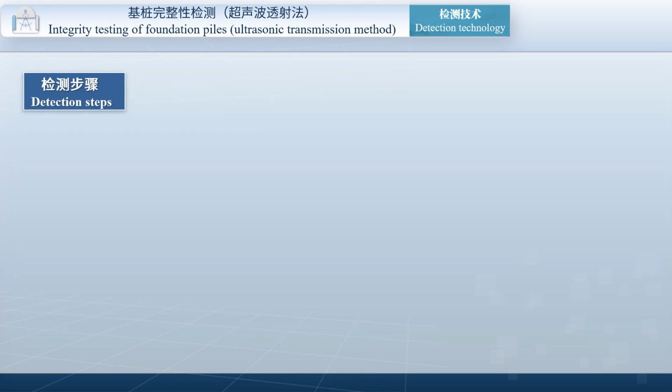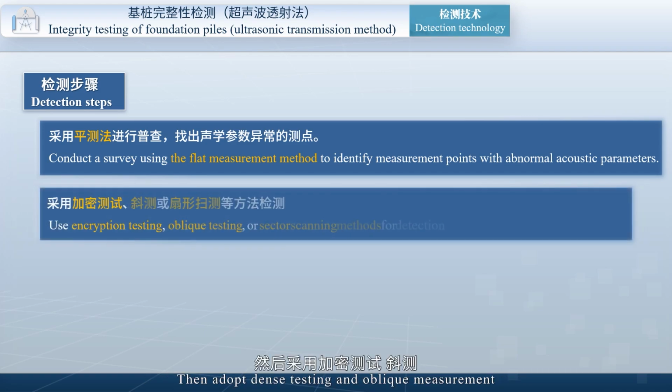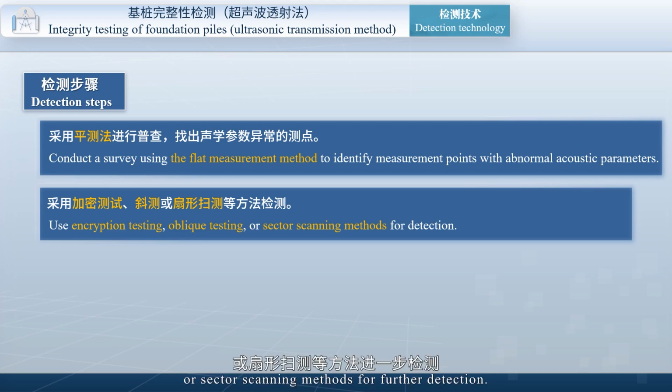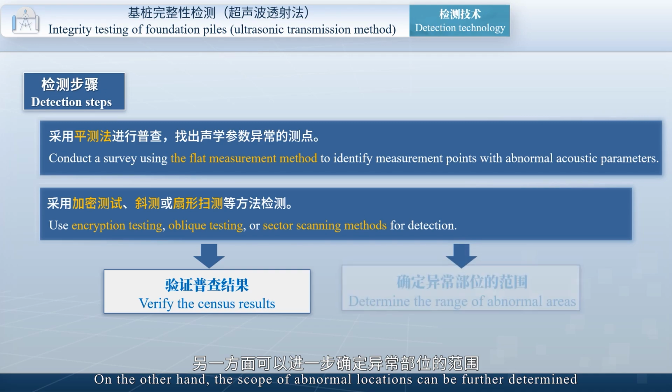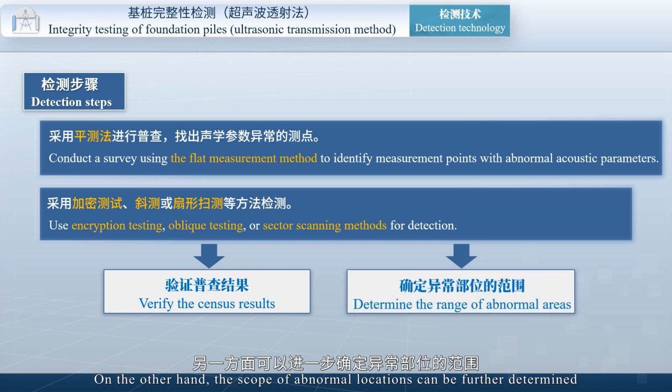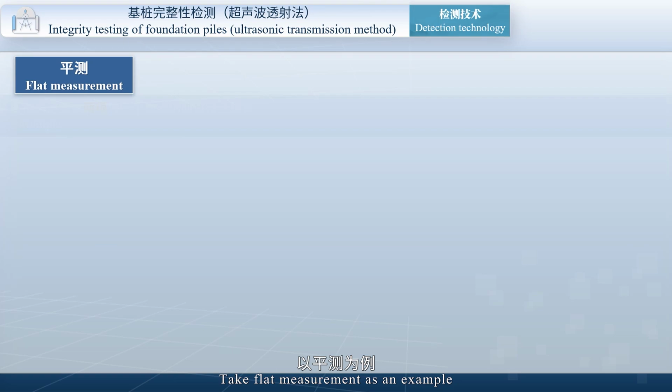Detection steps. First, conduct a general survey using the flat measurement method. Identify measuring points with abnormal acoustic parameters. Then, adopt dense testing and oblique measurement or sector scanning methods for further detection. On one hand, it can verify survey results. On the other hand, the scope of abnormal locations can be further determined. Take flat measurement as an example.